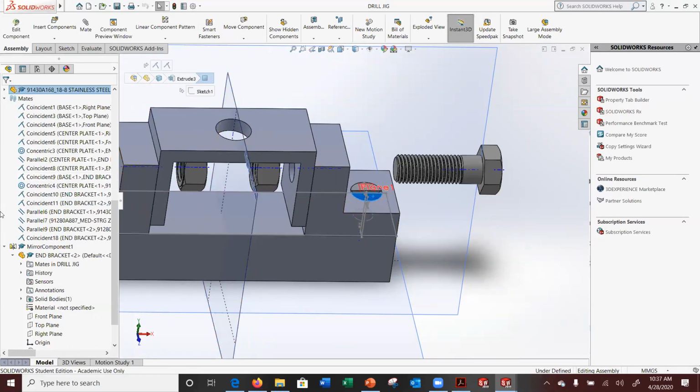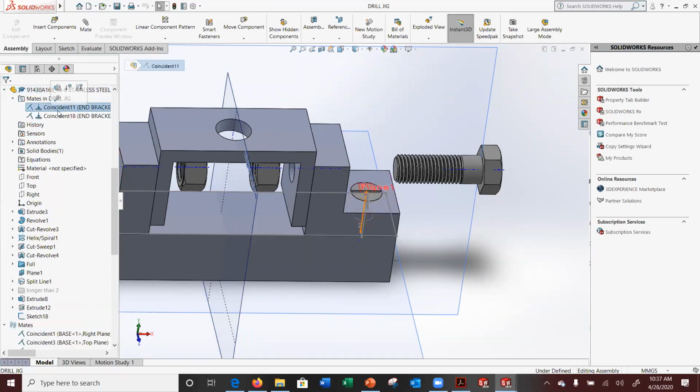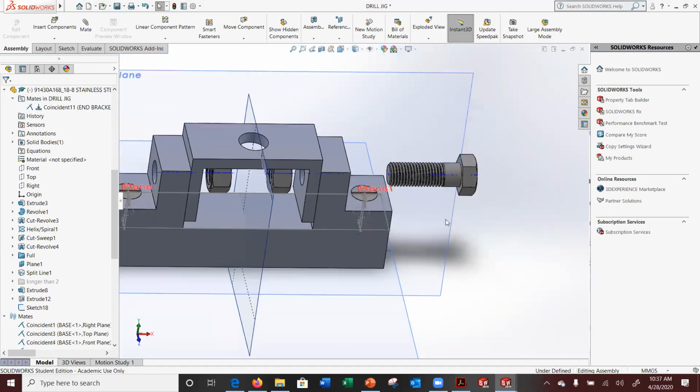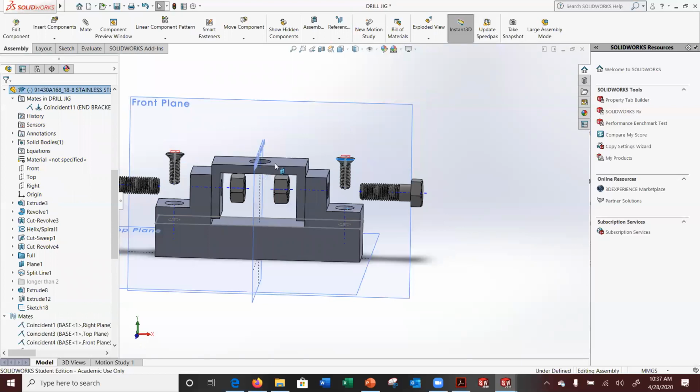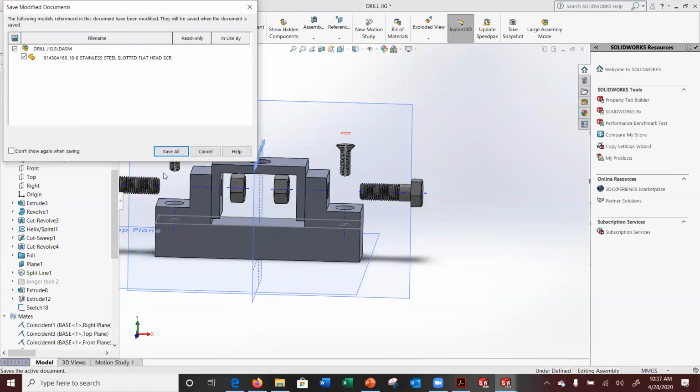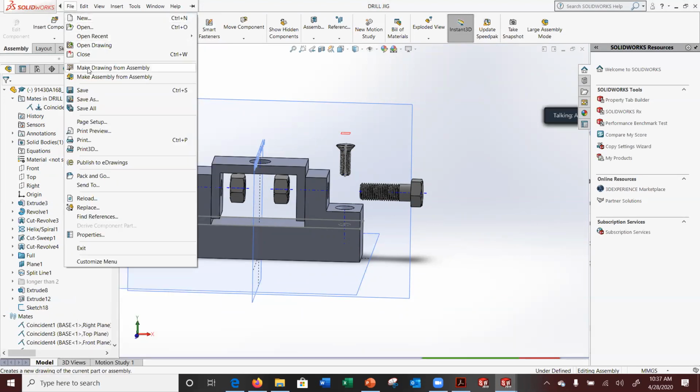One thing I do need to do is pull these back out, because that was the other advice that I gave you, to make sure not to put these in the part. They'll make your assembly look less cluttered if you have them pulled out. So it has to be exploded. For the assembly, I know it's a visual thing, because normally when we do hand drawings, like in the hand drawing class, you could do a simple thread. In here, because these are literally threaded, it's not going to do that. It's going to actually show the thread, and I'll show you in a few minutes how that looks.